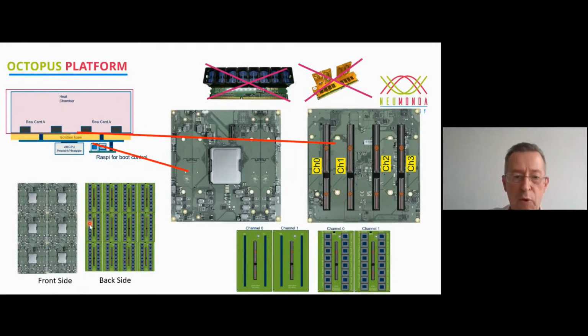You can place component sockets on what we call DOT boards. Then you can do component testing and don't need those nasty clamshell sockets anymore if you want to do component testing. You can use burn-in environment, loader, unloader for automatic loading, unloading. If you want to test modules, then you simply unscrew and replace it with module slots. Then each of those DRAM component sockets is replaced by a module slot. So both you can do module and component testing.